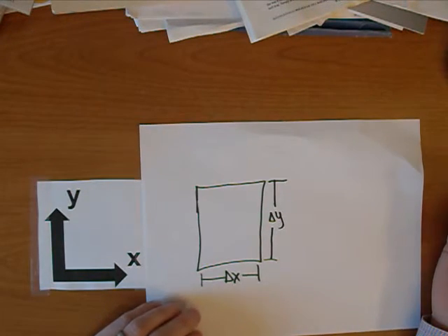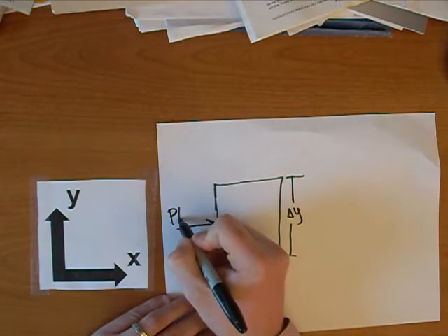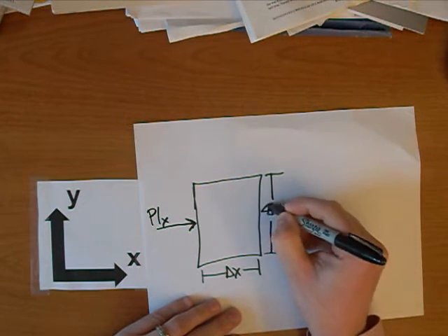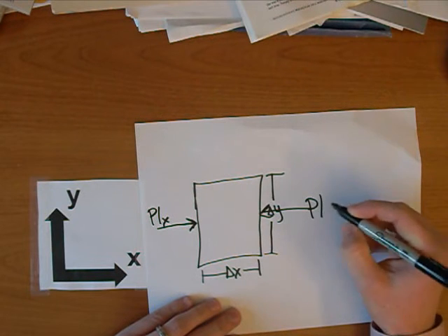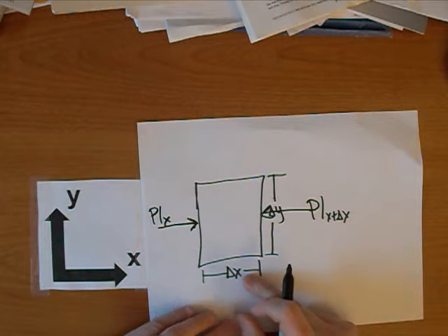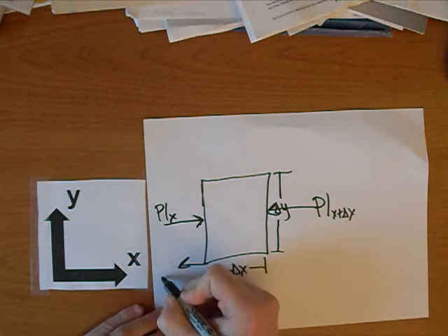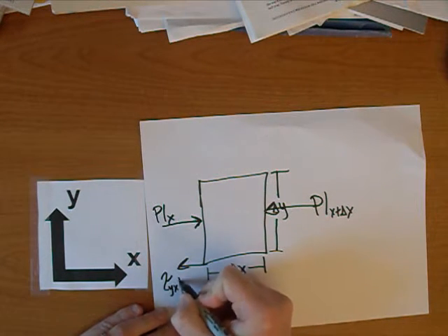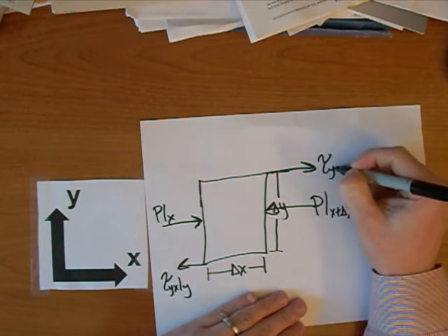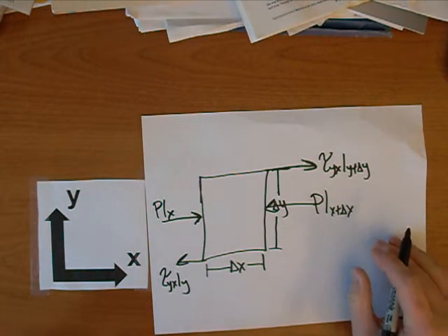And what happens is the pressure, as you've seen written, you have a pressure over here at x, then you have another pressure point pushing on this face at x plus delta x. Alright, and then you have a shear stress down on this bottom face, tau y x at y, and then you have one on this top plate, tau y x at y plus delta y.